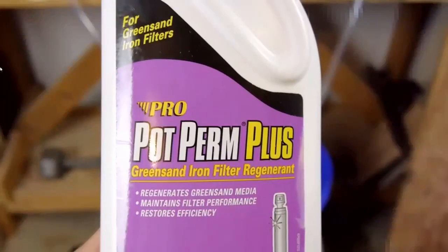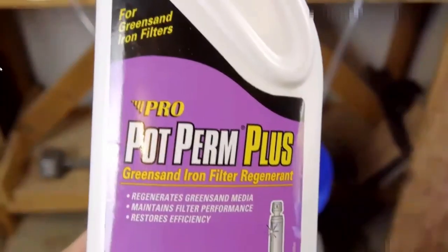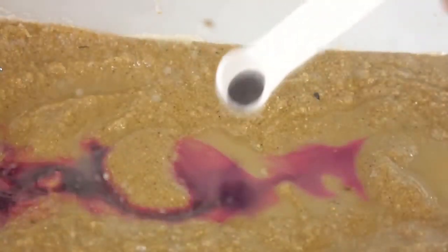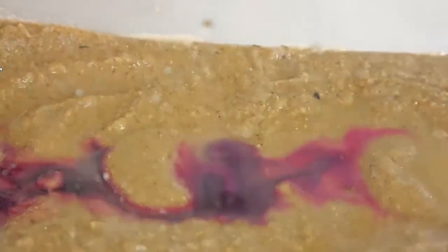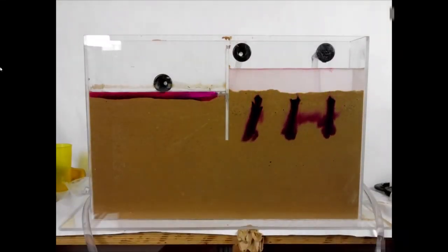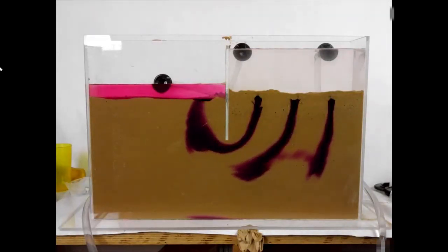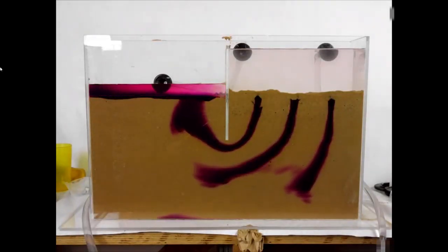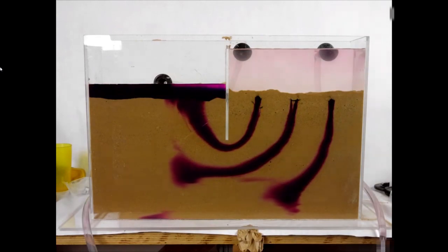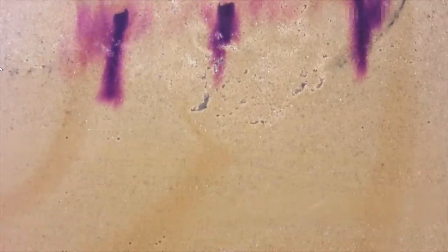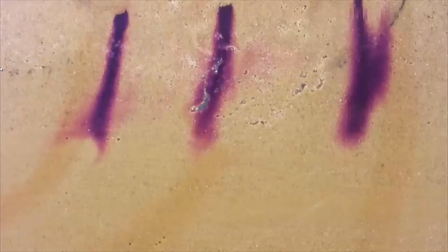Here's how it works. Potassium permanganate is added to 3 spots in the top of the sand. A pump in a bucket below keeps a constant head pressure on one side of the model. The differential between the water level in both sides is what drives the water to flow from one side to the other. Groundwater flowing through the sand creates traces of the flow lines over the course of several hours, illustrating exactly what we estimated earlier with the flow net.